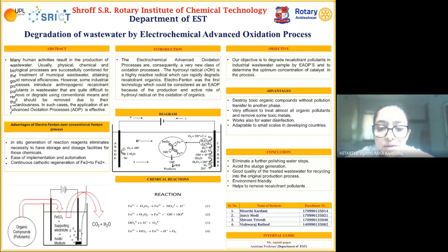For that, initially we measured a few physicochemical characteristics of water such as pH, COD, BOD, color, etc. In the process, 750 ml of textile wastewater was considered for all the electrolytic experiments, which were conducted in a 1 liter capacity cylindrical glass cell. As anode, galvanized iron was used and stainless steel was used as cathode. The depth of immersion of all the electrodes was kept constant at 8 cm and the clear spacing between the electrodes was kept constant at 2 cm.